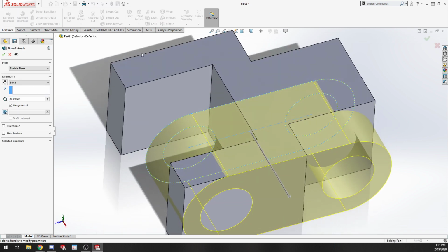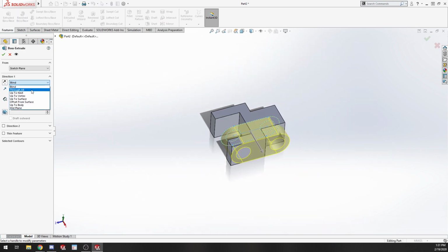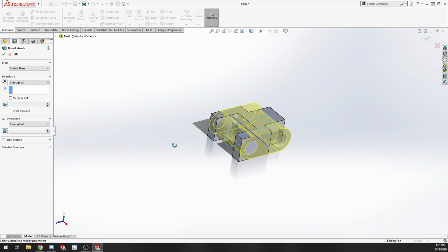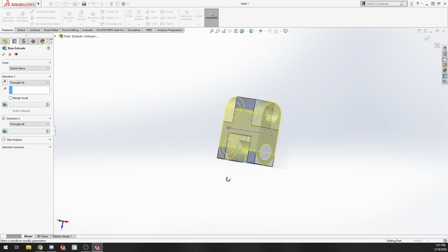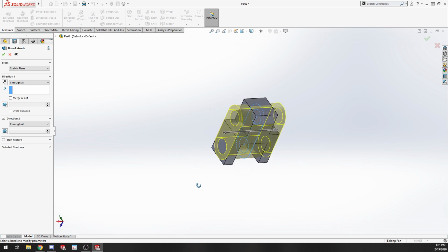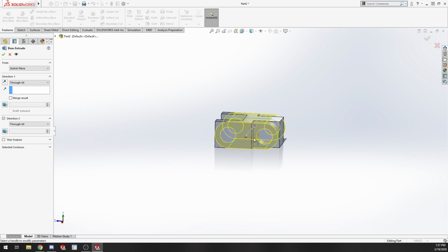So if you guys remember, last time we were talking about direct editing. Basically what I'm doing here is, the first sketch that I made was a top view of my chain link, and this is my side view. So it's rounded out on both edges. Got those circles there. I used the slot feature because that gave me a center line to go off of, so I could place my holes concentric to that radius on the outside.